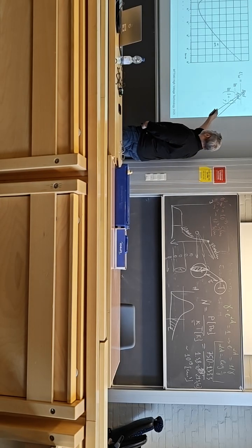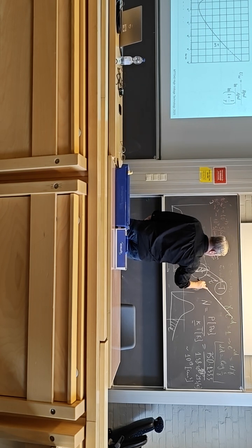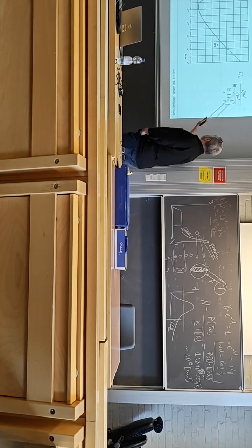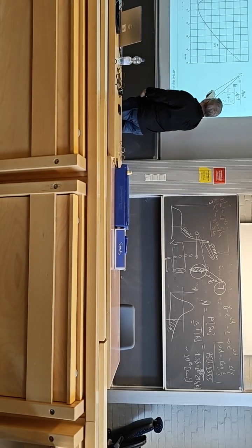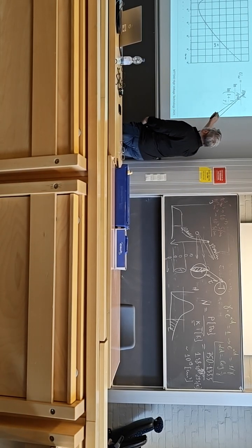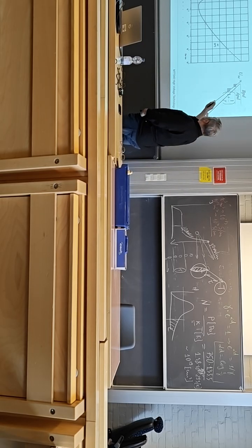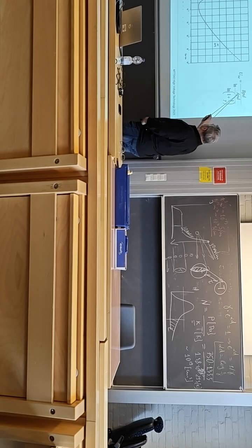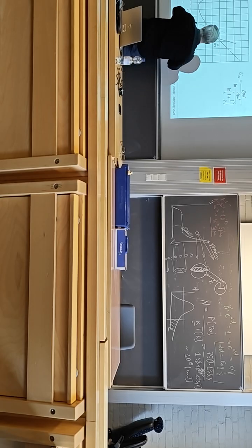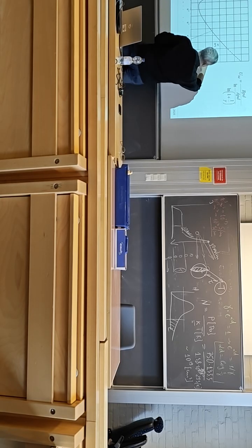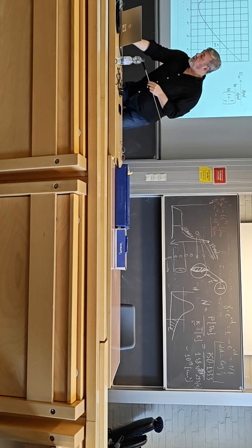So A and B are empirical coefficients describing the alpha, basically. But this is just the formula which shows that breakdown voltage is proportional to the product of pd. And then in the denominator you also have the log of pd. That's what brings some kind of nonlinearity. Otherwise it will be just a straight line.